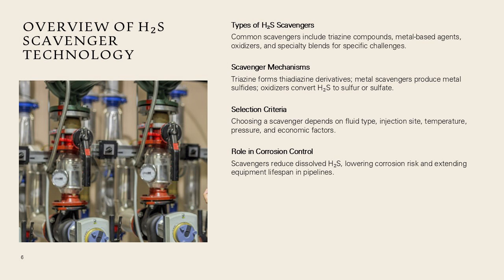and compatibility concerns. The selection of an appropriate scavenger depends on factors including fluid composition, injection points, temperature, pressure, flow regime, and economic considerations. Scavengers are integral to broader corrosion control programs by reducing the presence of dissolved H₂S, thereby lowering corrosion potential and extending equipment life.